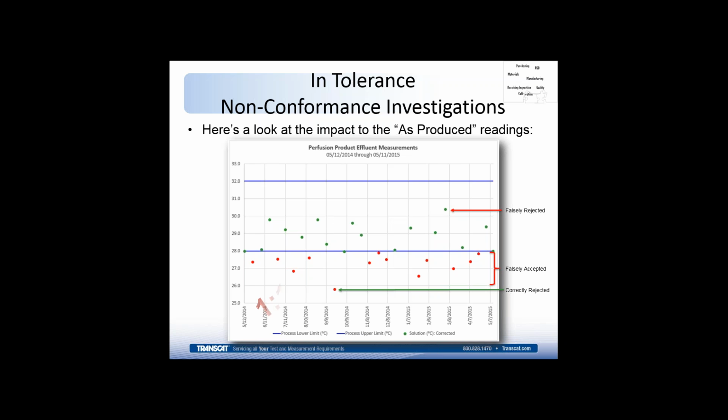So in a one-to-one situation, it's too risky. You've got too much variance there, too much ability for the instrument to move within its allowable range and still cause an impact to the measurements on the product over the cal interval of that instrument.